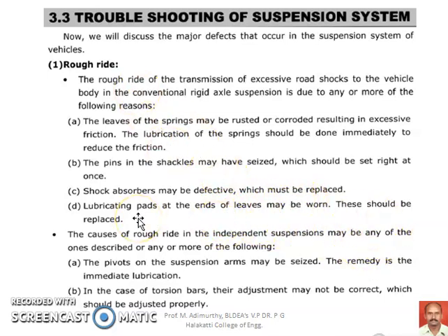In case of independent suspension system, the reason for the rough ride can be that the pivots of the suspension arms may be seized. So the free movement of the arms will be lost and it leads to the rough ride, and the remedy is immediate lubrication for smooth movement of the arms. In case of torsion bars, if the adjustment is not correct, then it will lead to the rough ride, and proper adjustment is required to get the proper ride conditions from the suspension system.